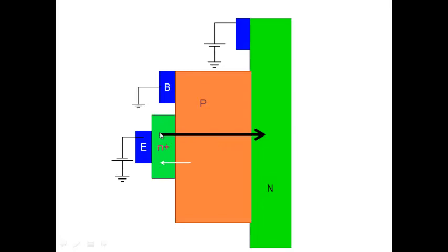Okay. Now you may question why, for example, let's say you have injected an electron, why does it not go here? Why does it go all the way here? What are the dimensions as I go here? This is like 1000 angstrom. And what are the dimensions here? Microns. This contact could be 2-3 microns away. So when you look at the diffusion process, the electrons would diffuse quickly to this particular boundary here, rather than going all the way here and then eventually recombining with holes and all that. Okay, so that's what happens to the electrons.